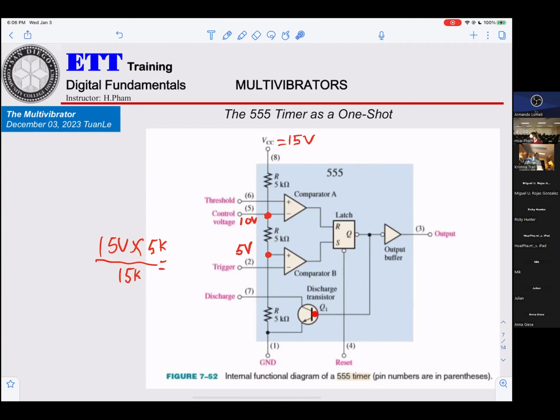What happens if it is turned off? And when will it be turned off? And what happens if Q1 is off? Okay, and you can see there is one line in here called reset. That means they want to reset this flip-flop. They connect it to the ground, so the output has to be 0. Okay, any question up to that point?